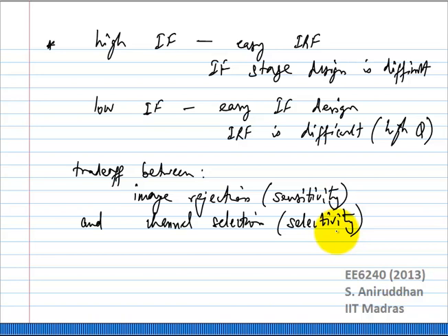Okay, so now obviously designing your image reject filter is not straightforward. Especially if you want to choose a low enough IF, designing your image reject filter is not at all straightforward, and in most cases people would go in for an off-chip filter. However, we know that CMOS is not well suited to drive 50 ohms. You do not want to have off-chip components, so you actually need to come up with some architectural level solutions apart from circuit level solutions to target the filter itself. People have come up with architectural level solutions to combat this problem.